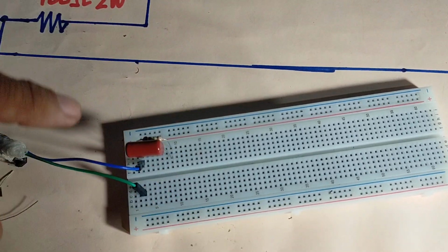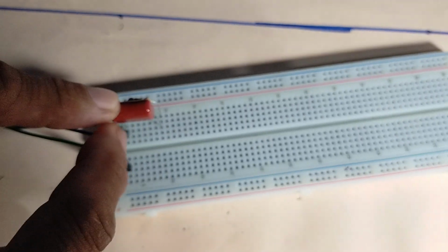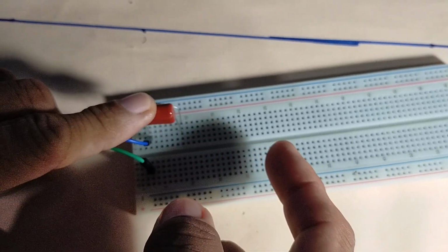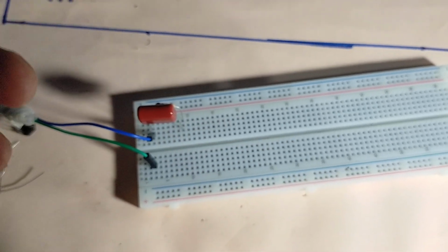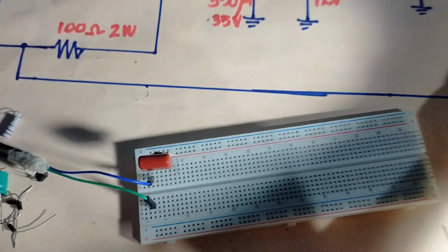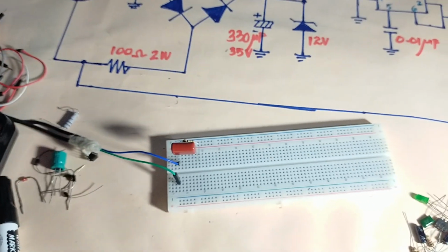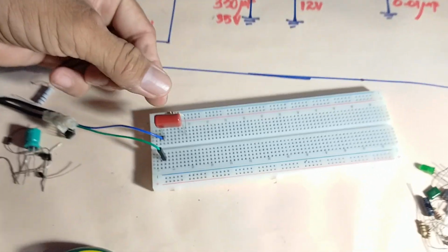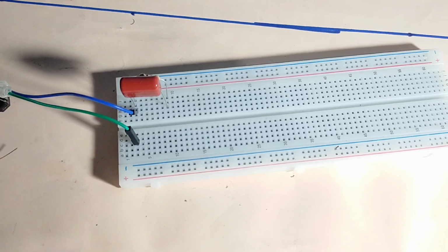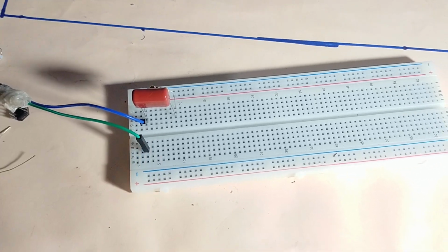Okay. Remember that this capacitor is a voltage dropper. It drops an amount of voltage so that there is a lower remaining voltage at the output, which is needed by the load resistance here, which is the appliance protector. And actually the purpose of this resistor across the capacitor, as we have studied before, is to discharge the voltage, because this capacitor will always store charge, and that voltage being stored by this capacitor should be discharged.